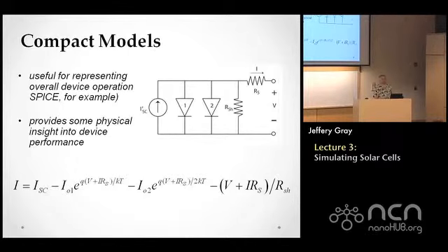And then series resistance, and series resistance typically comes from the sheet resistance of the emitter layer, because you have a front grid, which you'll see here in a minute, where the current has to flow laterally, and that gives you some resistive losses. The grid fingers themselves, the metallic grid that you attach to make electrical contact, will also add some series resistance. And so it's very common to use a model of this form to be able to predict what the IV characteristic looks like.